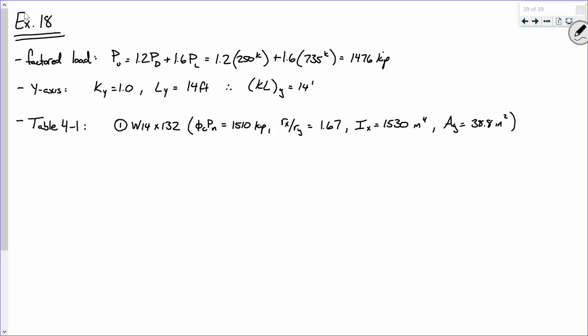W12 by 152. So are you all in agreement that the W12 by 152 is the lightest W12? Okay, W12 by 152. Keep that in your head. Now, everybody over here, what is the next W14? We have a W12 by 130, or W14 by 132. What's the next W14? 145. Okay, so here's what I'm proposing.